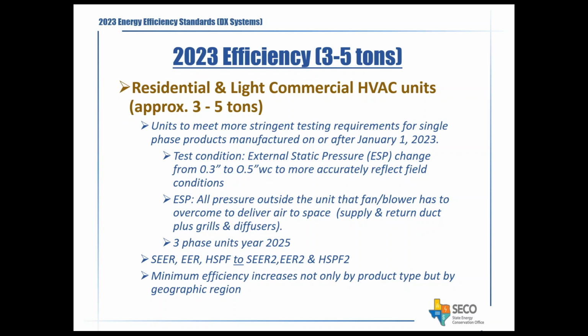And one other thing I'm going to describe: what you see as SEER, EER, HSPF. They have some new designations, changing them to SEER2, EER2, and HSPF2. I'll describe each one of them in a little more detail. These are the existing efficiency rating systems, and where they have the 2, that's the new ratings.